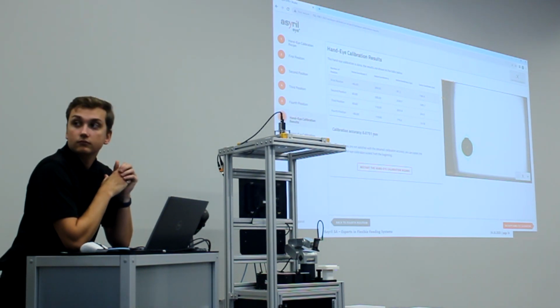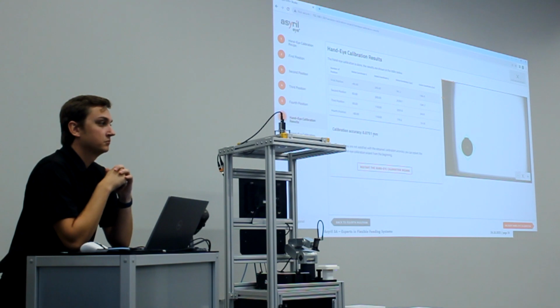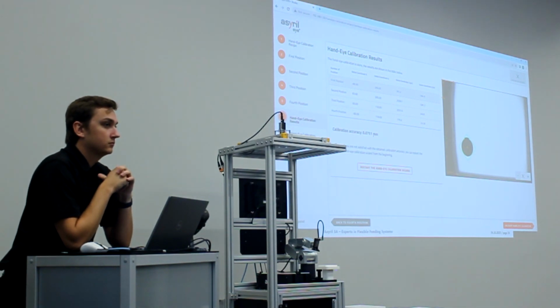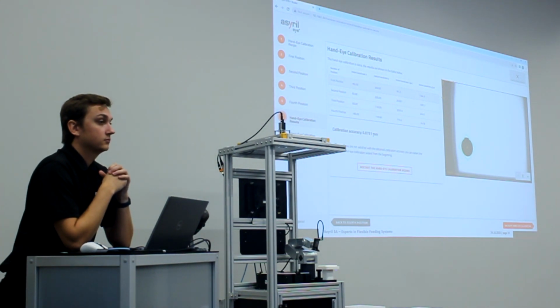We also offer advanced commands that allow you to automate the calibration process. So if you are able to accommodate a part on a pedestal in your application, you can teach your robot where that calibration part lives. So it can go and grab it, and then you can automate the entire procedure of placing the part in each of the 4 corners and collecting an image.